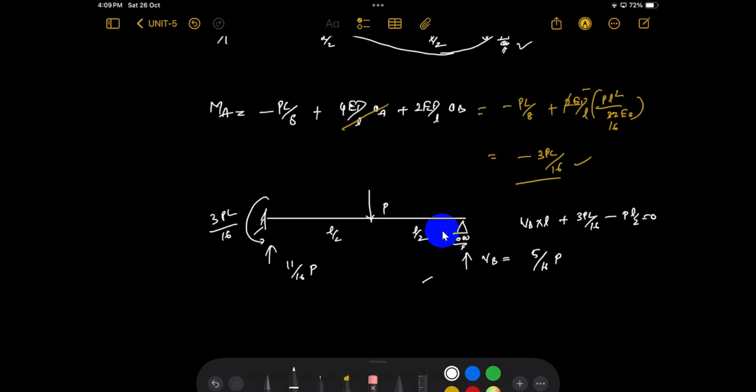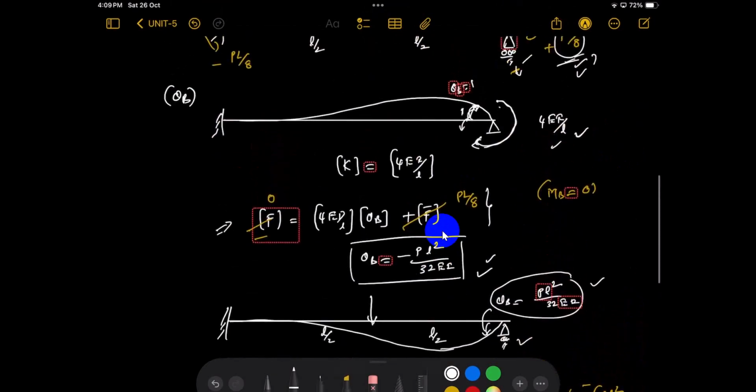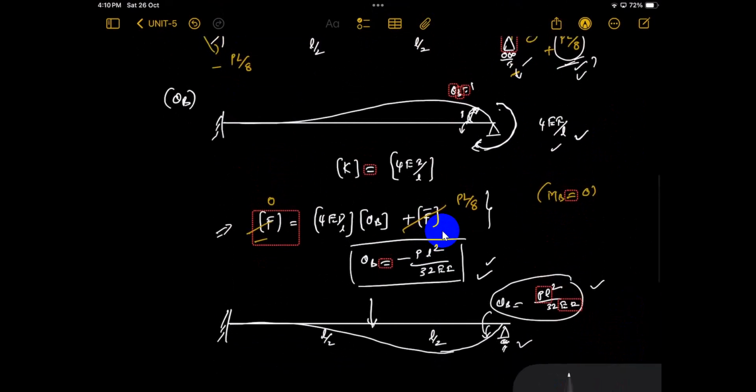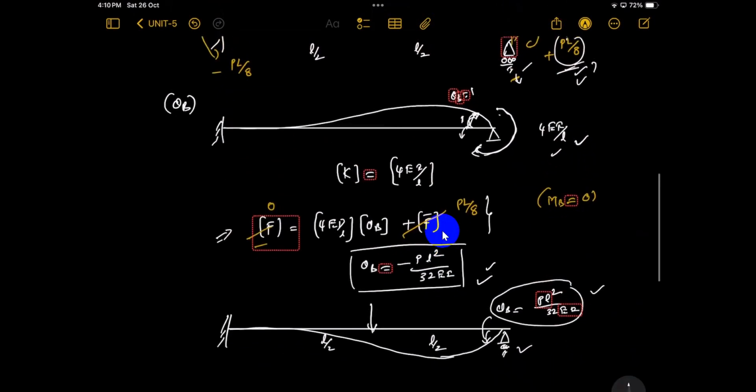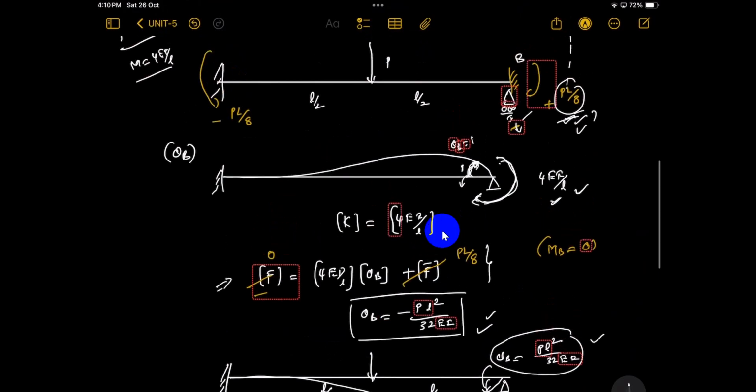We analyzed it. So just feel the understanding of what the equation means. Understood? Per 1 unit rotation you will get this much amount of force. How much rotation occurs to nullify this amount of bending moment? Because if you prevent the rotation at the joint, you will get this much amount of moment.